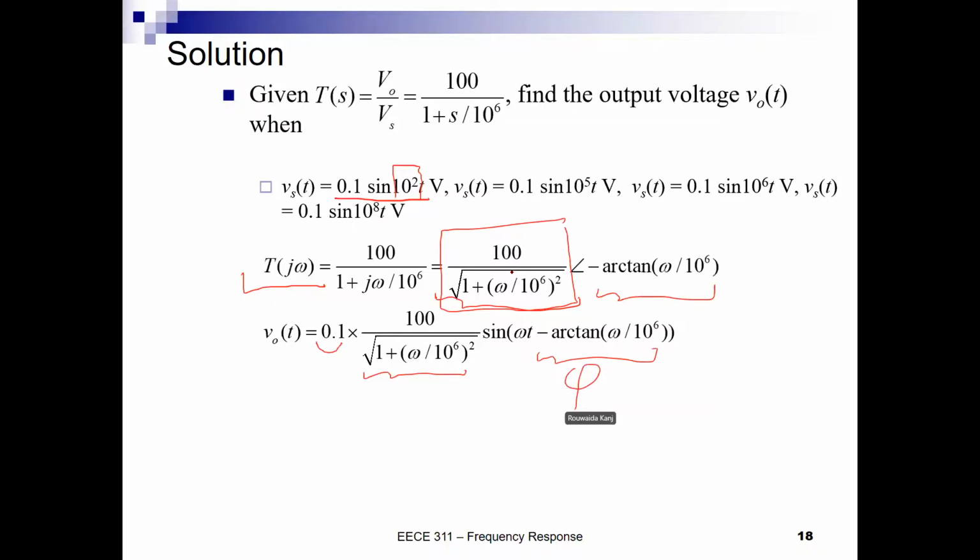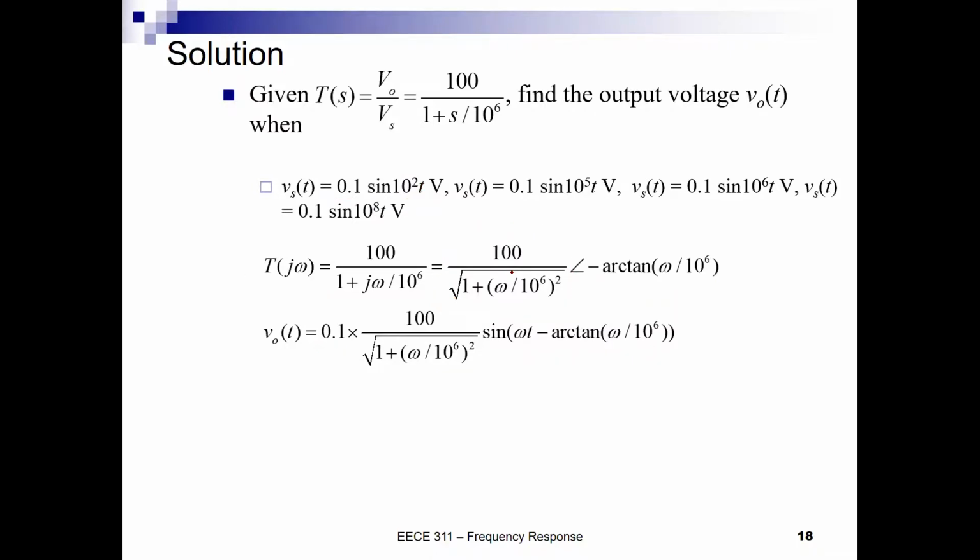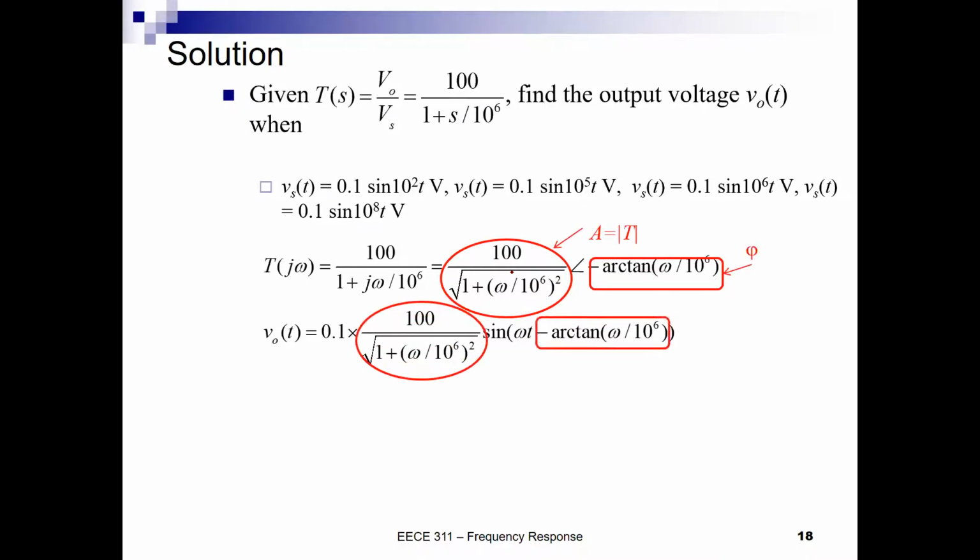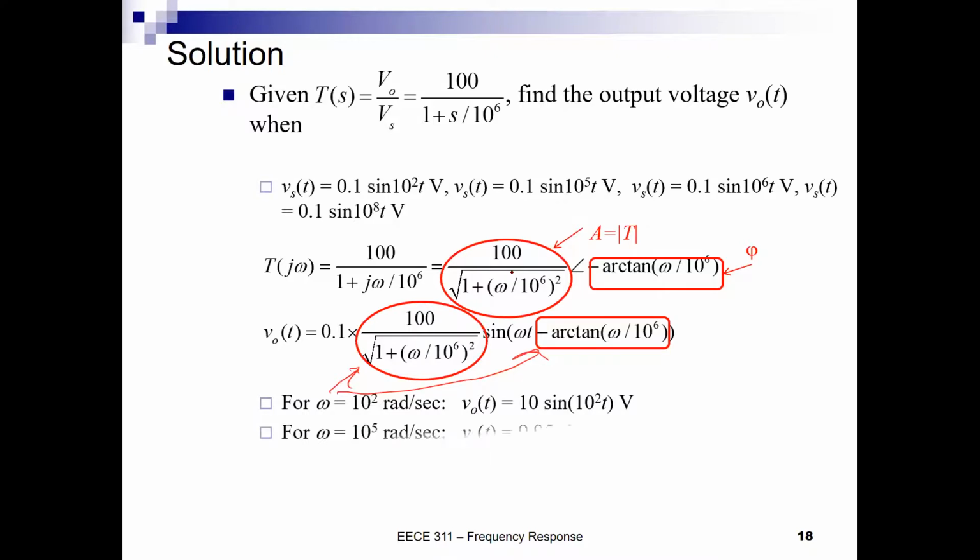Okay, so this is what we explained a little bit ago, and we said that this magnitude and this phase are going to pop up here and here. And then we started to calculate, well, if I plug in directly into this red circle and into this here to find what the magnitude and phase will be at a specific frequency omega, here the magnitude will be 100 and the phase will be 0.